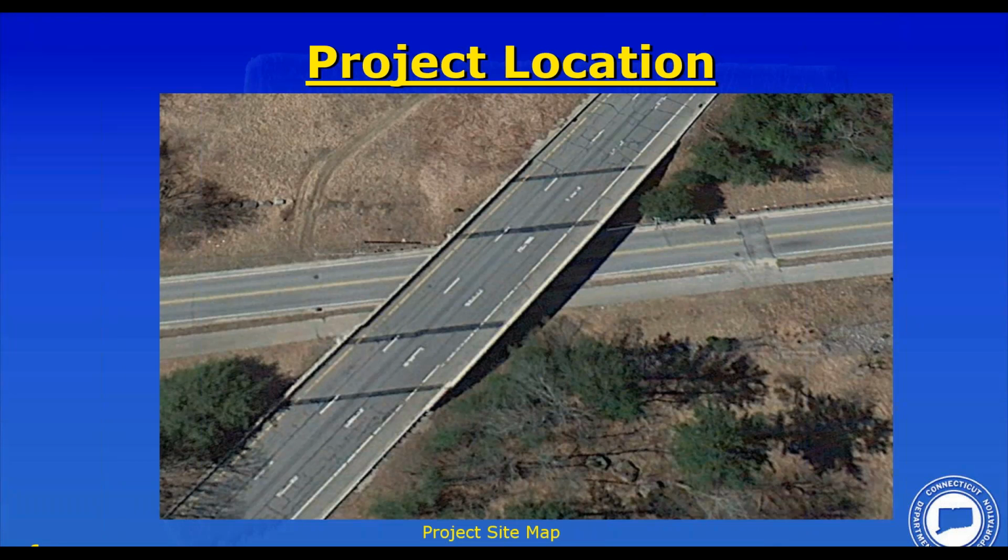Zooming in a little closer on the bridge, the traffic volumes are fairly low on 395 in this area. However, you might say, wow, look, Mike, there's 3 lanes of traffic on this bridge. It must be a high ADT bridge. The reality is we're fairly close to the acceleration lane from the on-ramp for the interchange just to the south of the bridge. So this particular bridge has a climbing lane or an acceleration lane that goes across. So the third lane is not necessarily there for ADT. It's really there for the acceleration of vehicles coming up the highway.